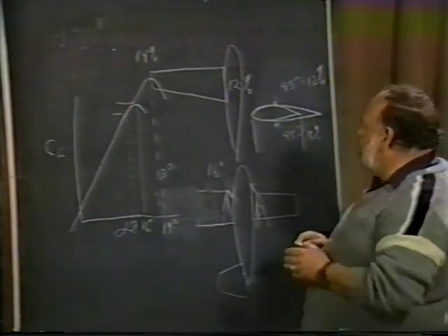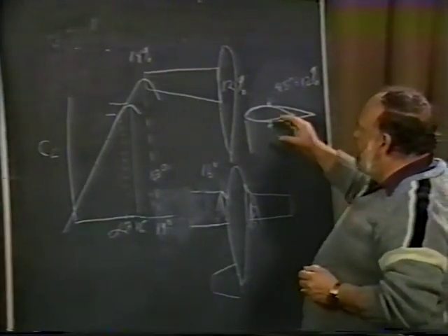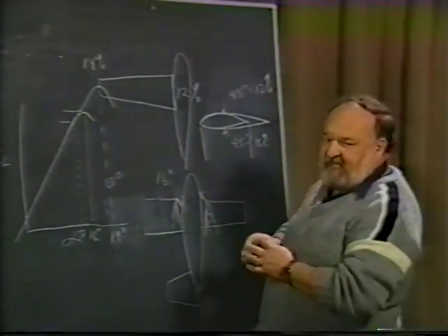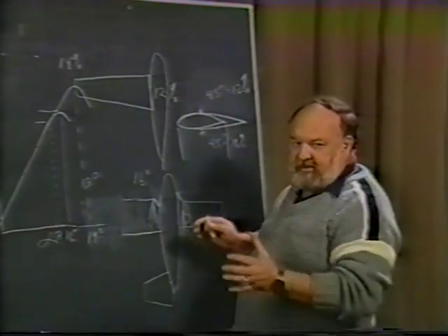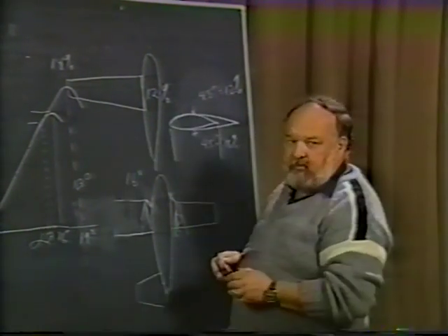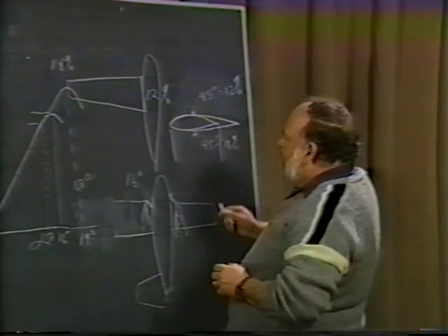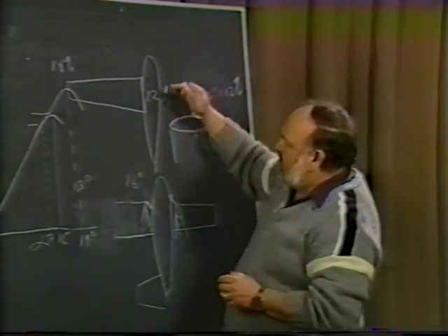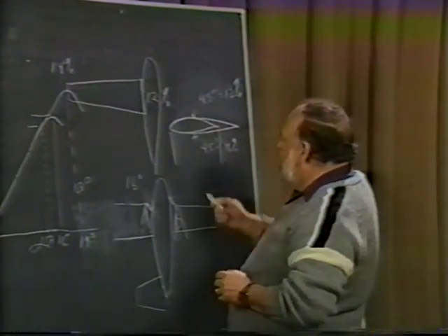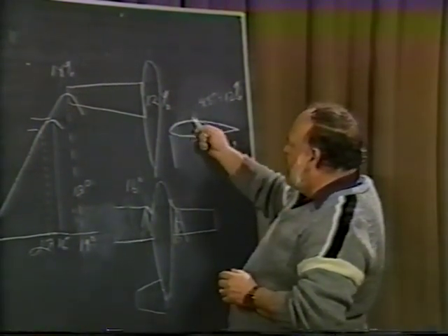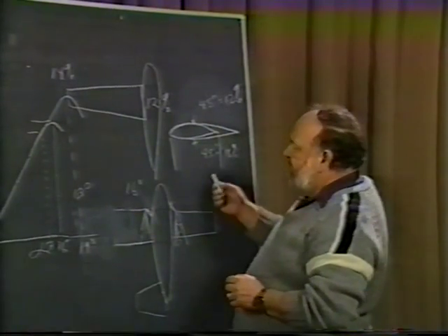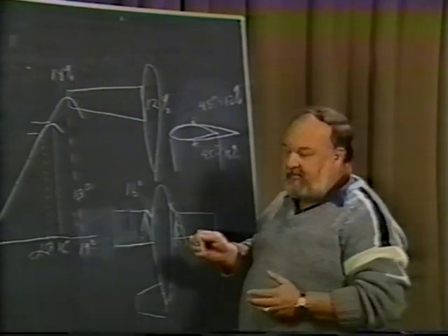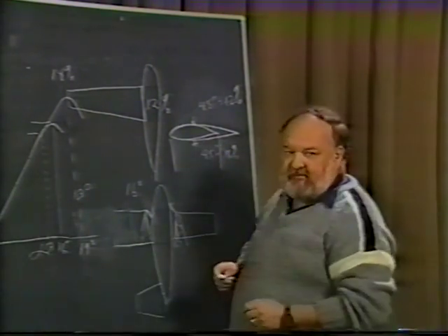So here was a situation where we had a wing design that was tapered, which gave us certain little advantages of being closer to an elliptical lift distribution for the whole wing. Yet it was easy to construct because we had almost the same leading edge radius. It was straight and smooth throughout. We had an equivalent thickness of the wing all the way, about 4.5 inches throughout. So in that case, whether you use a tubular spar or an I-beam spar, whatever it is, you now can have a straight spar. You don't have to bother tapering it.